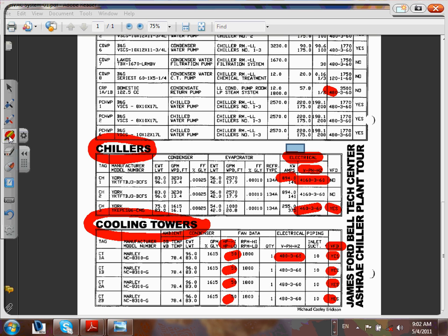If you guys know how to read this, you can hit the ground running in any commercial project. It really is. Done. That's as ugly as it gets in a commercial project, the heating cooling system. I want to bring to your attention, Ryan, my friend, that cooling towers are motors, and you guys know how to size everything for motors, right? We know how to size the branch circuits, the disconnect, the overcurrent protection device, the controller for motors. So these are motors, done.